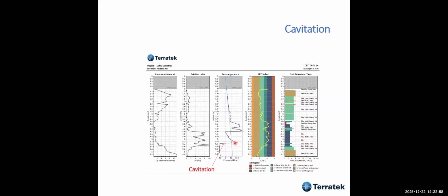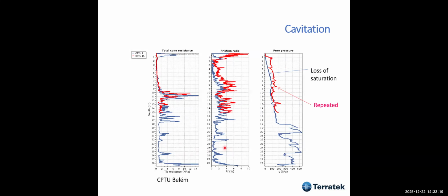And that's why you have to use pore pressure information with care, okay? And in the past, people dealing with offshore used pore pressure for classifying the soil. Today, we tend not to use it because sometimes we cannot trust the results because of cavitation. This is impossible to do.